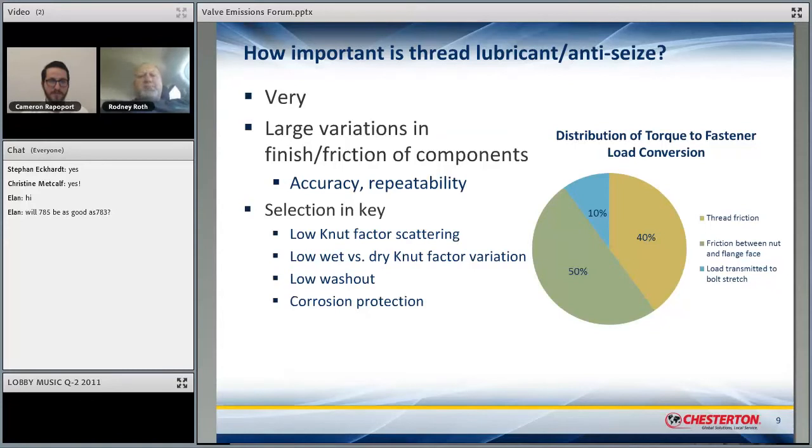So the fact is that once that stuff starts to heat up or it starts to sit out in atmosphere, those wet lubricant components of that, the liquids or the greases or oils or whatever it's made from, depending on whose it is, those are going to dry out, and then you're going to be left with just your solids component, unless those materials that you use in there are not completely cooked out and it's not completely dry.